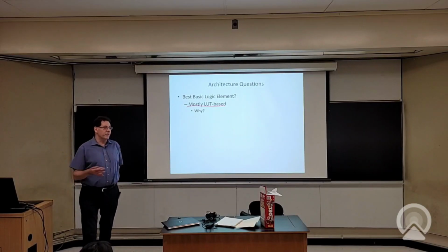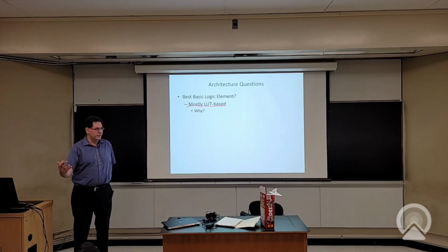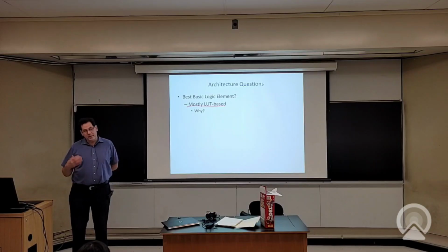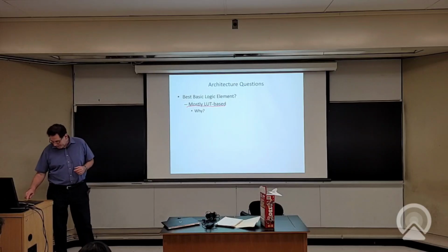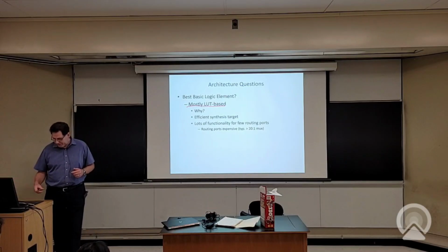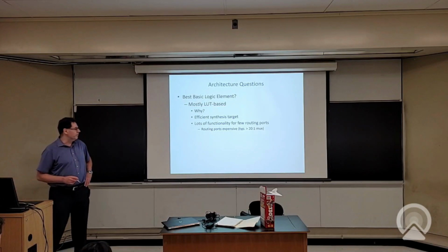It's a very efficient synthesis target, right? If you have k or fewer inputs, the logic function goes in, and you get a lot of functionality for the number of routing ports you have, like the most functionality you could have, basically. Any function with that many signals you can implement. So that makes it pretty good, right? It's an efficient synthesis target and lots of functionality for a few routing ports.